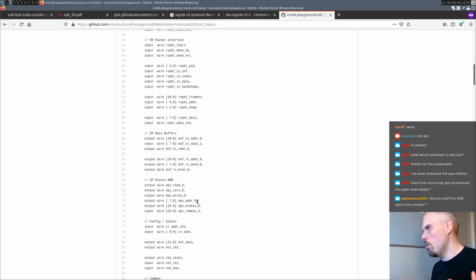First, it wasn't a generic USB core. It was designed to do one thing, and that thing only. And it also had a very hard time meeting timing on the UP5K, because it was designed for the LP variant of the ICE40, which has a faster fabric.